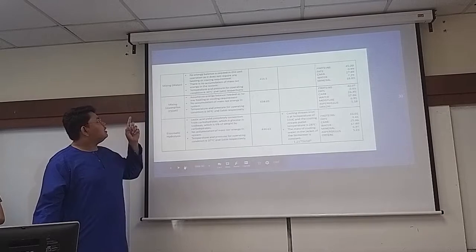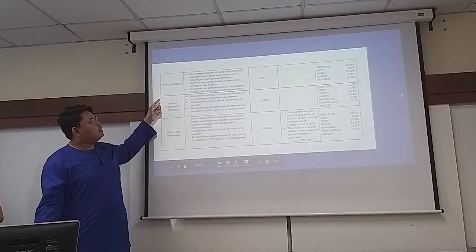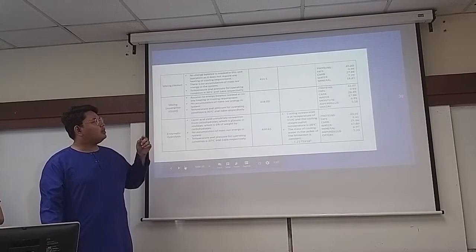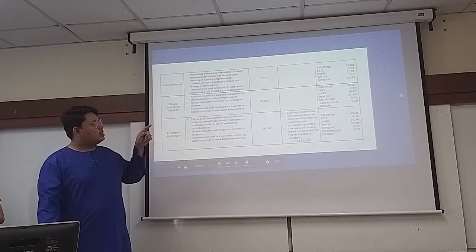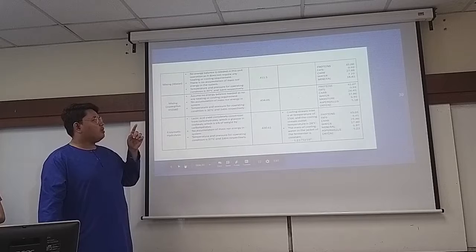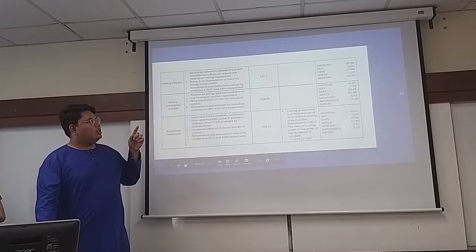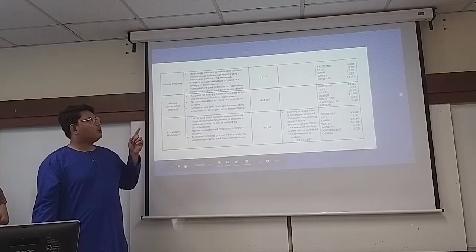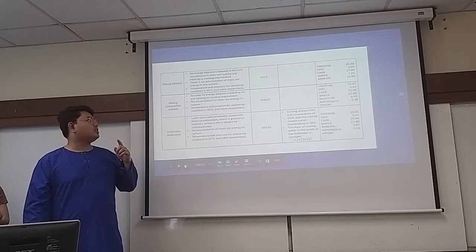So for the mixing, the first mixing is with the water. The overall mass balance is 411.5 kilogram per hour, and then there is no energy balance, and the composition is protein 45%, fat nearly 1%, carbohydrate 27.89%, water 7.29%, mineral 18.83%.